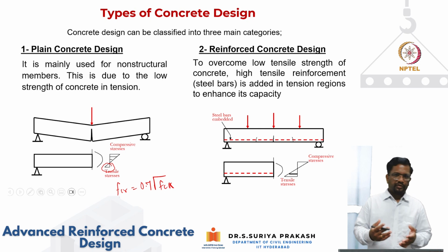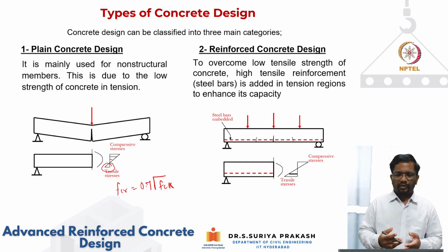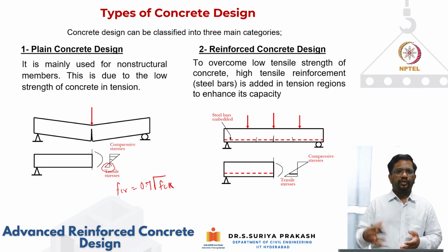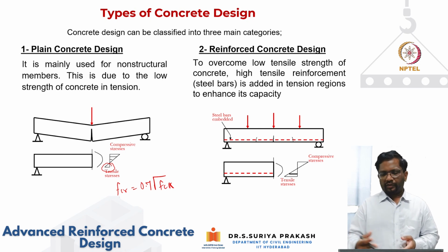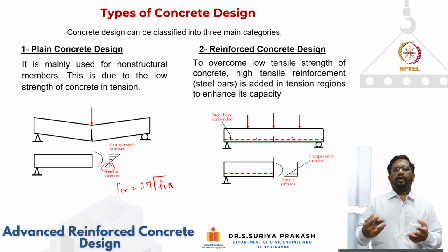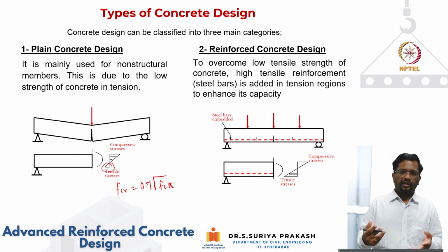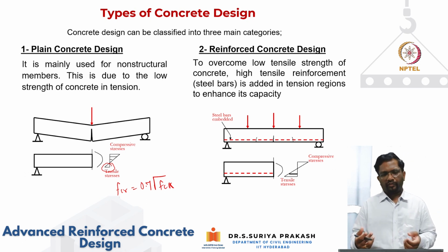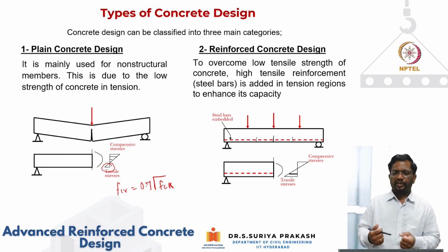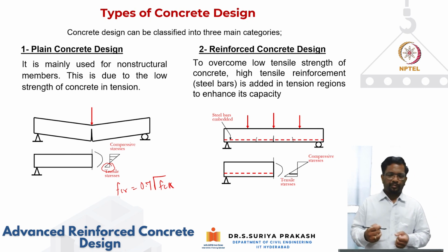Next is the reinforced concrete design. That is what we are going to go through in this course for various load actions. So usually what we do to overcome the low tensile strength of concrete, high tensile reinforcement in the form of steel reinforcement is added in the regions to enhance its capacity.